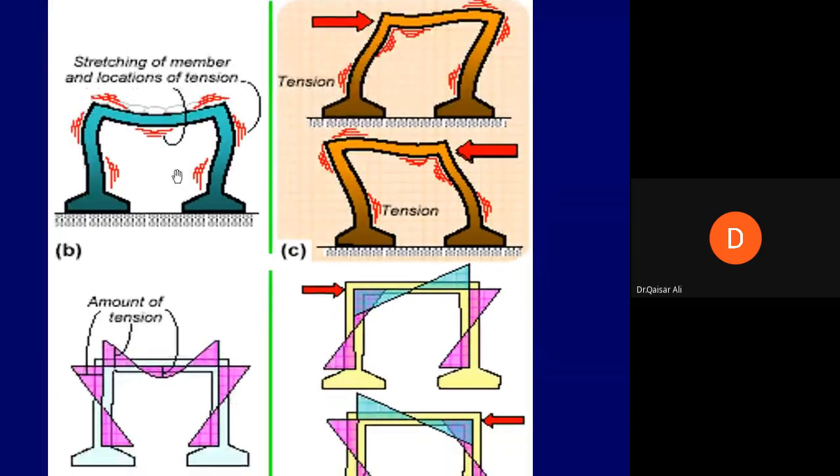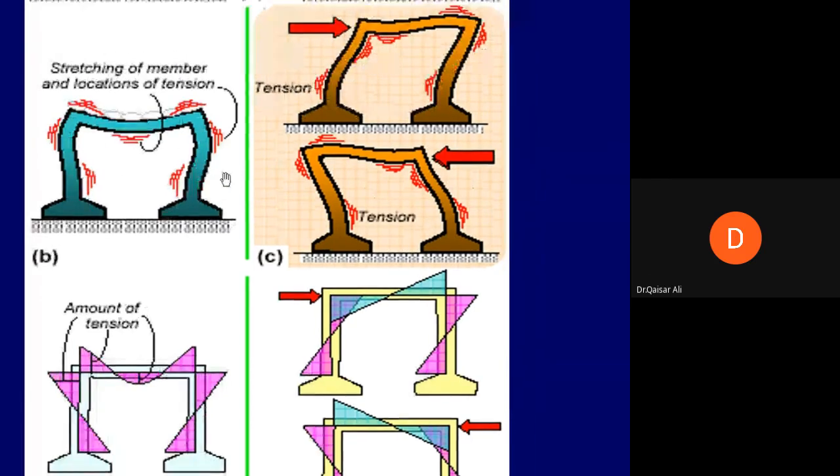Finally, what we will do is place reinforcement at the ends of the beams and also on all sides of the columns. The mid-span reinforcement will probably not change at the mid-span of the beam, and because in the column we provide reinforcement from one end to another, whether there is a bending moment at the mid-height or not is not of very much significance for us.